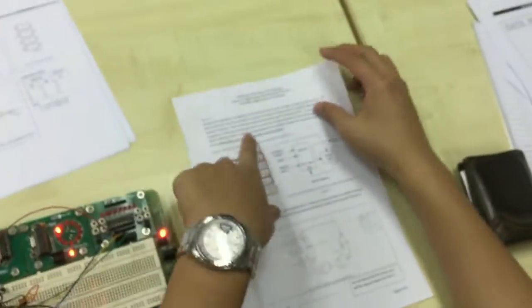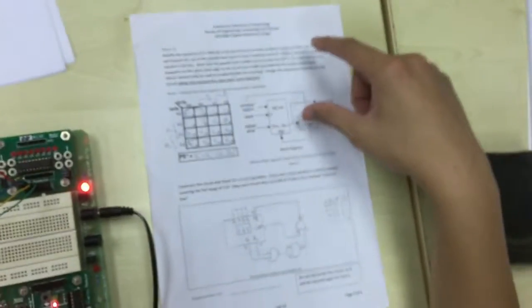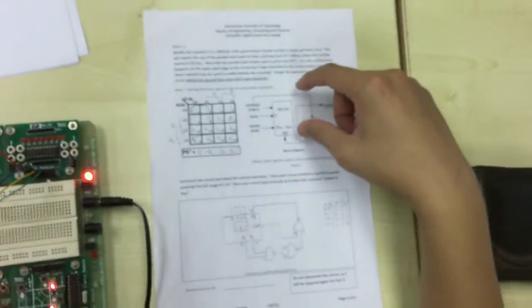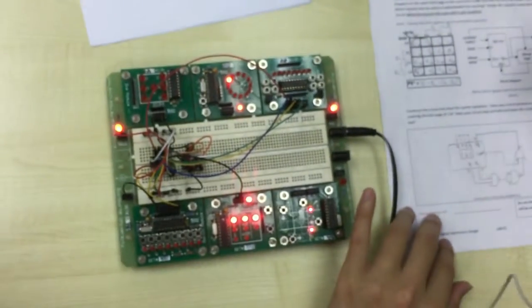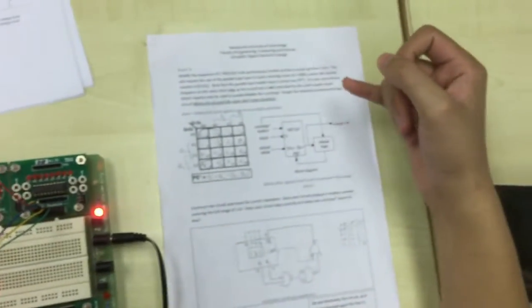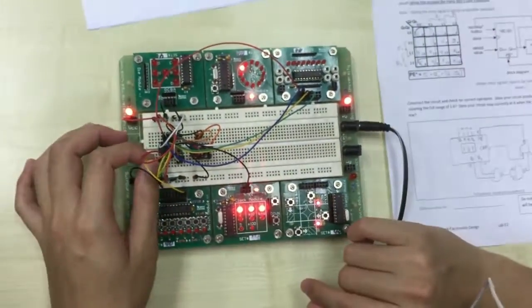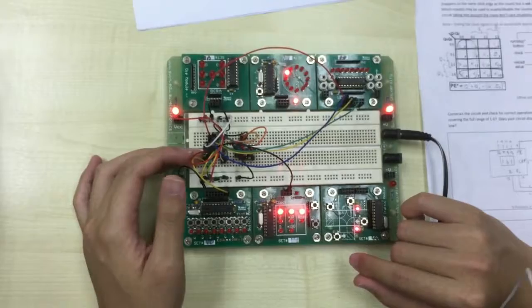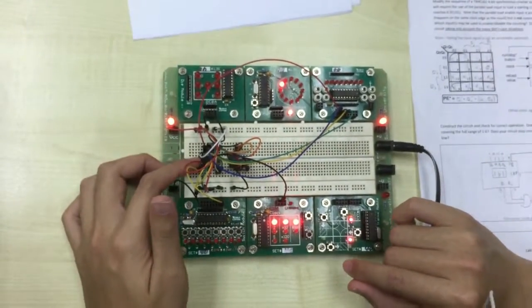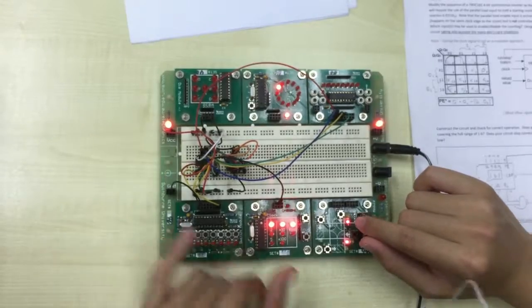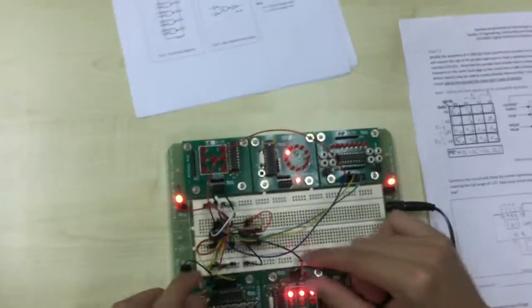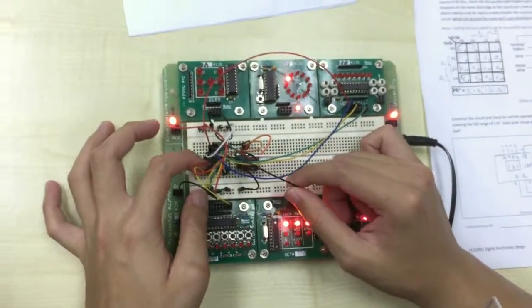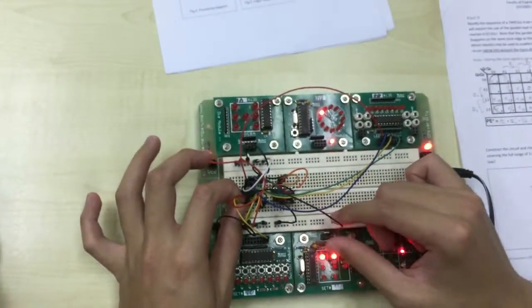Over again. Today I will discuss Lab 2 part 3. In this lab, we will talk about the 74HC161 four-bit synchronous counter that counts from 1 to 6. In this experiment, we use an HC00 NAND gate for us to count from 1 to 6. This is our wiring. As you can see here, this is our master reset. The master reset is connected to pin 1 of the 74HC161, and this clock module is connected to pin 2 of the HC161.